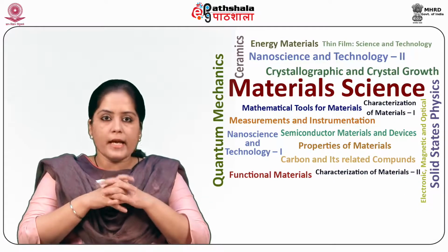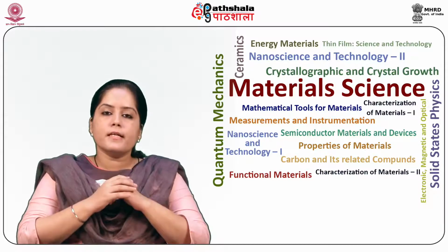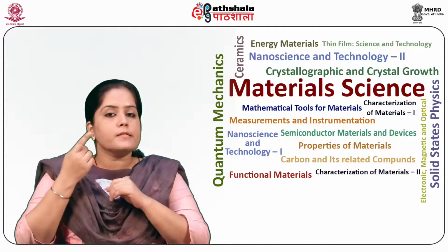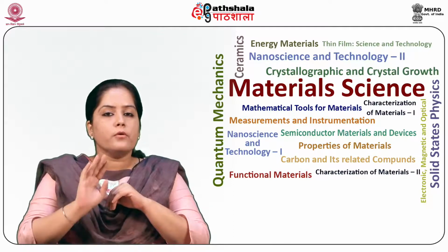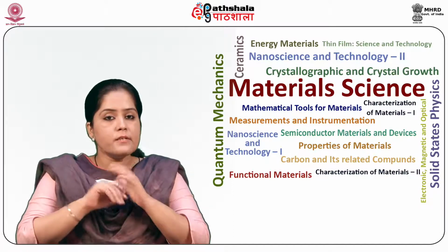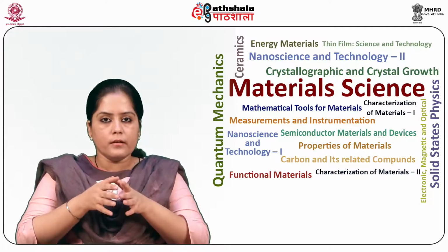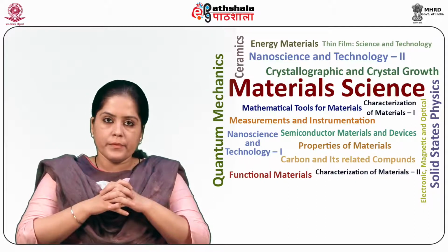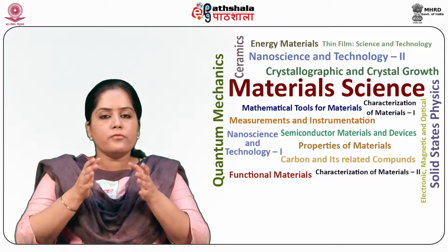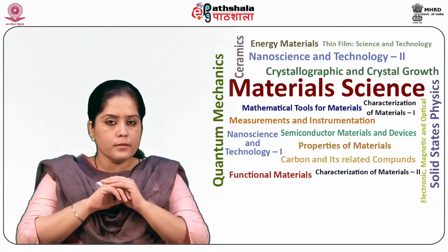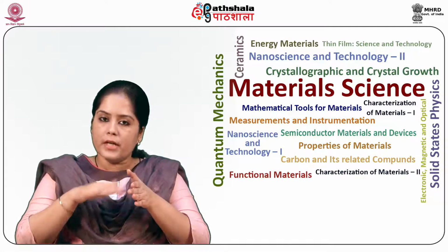Now let us discuss the advantages and disadvantages of thermal evaporation. First, let us discuss the advantages. It is simple and cheap, with less substrate surface damage and excellent purity of films. The disadvantages are that there is considerable wastage of source material during the process. Next, it is confined to low melting point metals. Evaporation of dielectric materials is not at all possible. The amount of material deposited is also constrained by the filament.